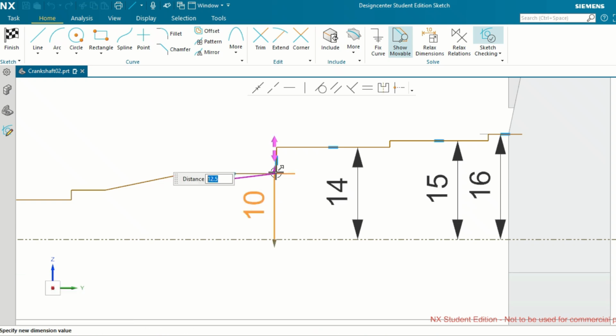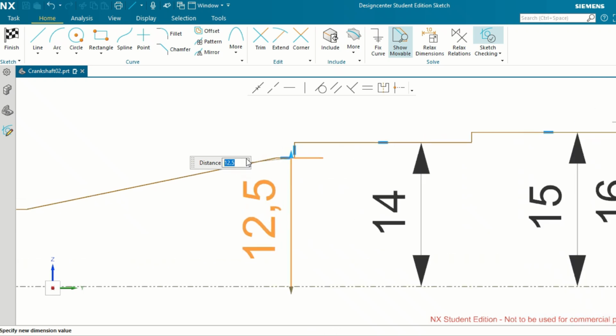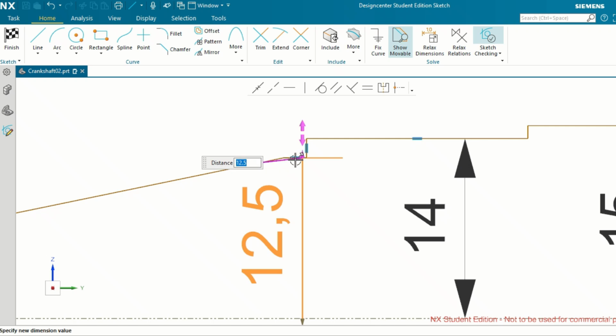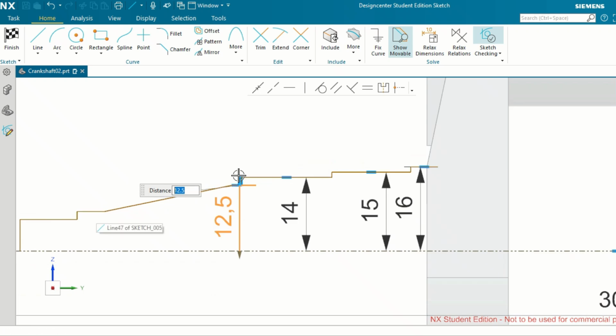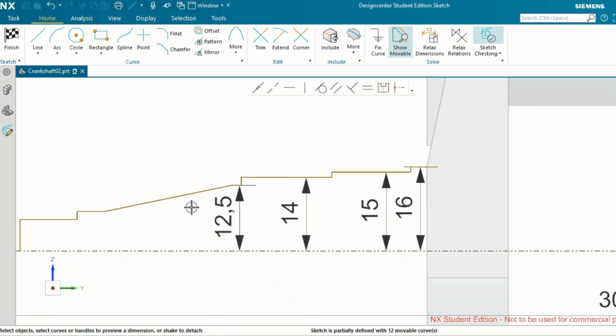You see the arrow mark and the anchor. This one shows the vertical relationship, and this arrow mark shows it goes up. We have to be very careful. Since I have not finished this dimension, this horizontal relation will apply to everywhere I am touching. That's why we have to finish this particular dimension, even though it's slow, no problem.